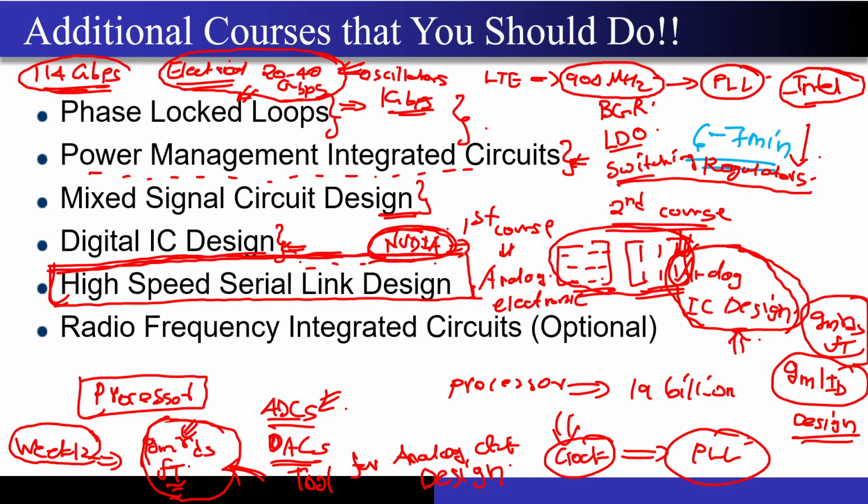So unless you have a good intuitive understanding of the 3 dB bandwidth and the gain bandwidth product of the circuit, that is the unity gain bandwidth of the circuit, and unless you know what this fT parameter is, you can never design these circuits. These are state of the art circuits, right? And this is a state of the art field. It is so state of the art that 2 of the people who did their PhDs in our group, in RF circuits, have been pulled by the company into this particular field. They had worked on RF circuits, but still they were pulled into this particular job.